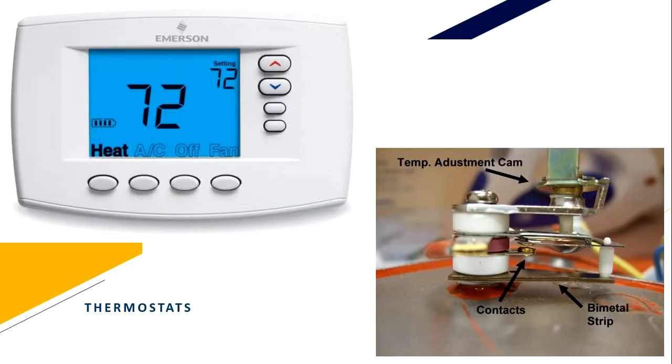Now, both the boilers and furnaces would operate all the time, and buildings would soon become too warm. We could use more fuel than necessary. So therefore, heating systems have a way to turn on and off automatically. A thermostat switch controls this process. The switch in a thermostat is often a bimetallic strip, as you can see here.